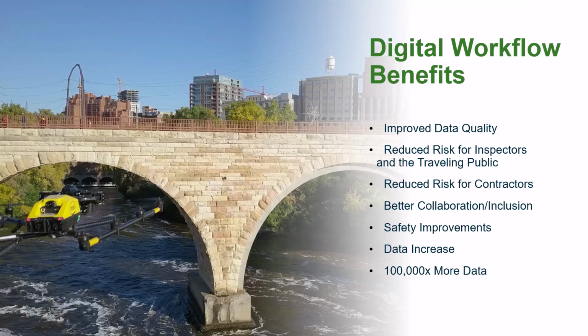For more routine situations, if you were just doing a routine physical tactile inspection, you could fly the drone up to the bearings and see certain areas. If you model the bridge, you can enter defects in without necessarily needing a snooper or traffic control. So if it's more of a routine inspection, you definitely have the ability to save more time and make a safer environment for both the traveling public and the inspectors.